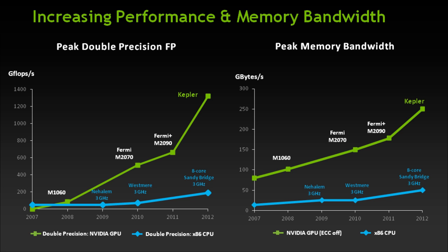If we were to consider a typical Nastran job, these are compute bound during the sparse solver phase, and other than the sparse matrix factorization, memory bandwidth and I/O performance are very critical. Ted talked to you about both memory and I/O performance. These are both very critical.